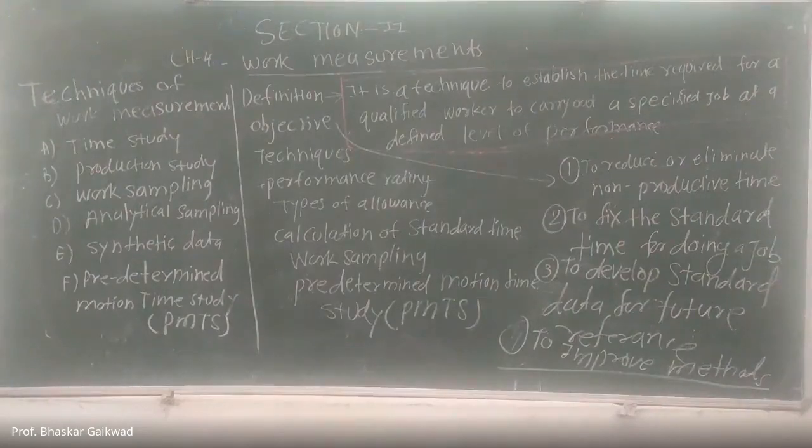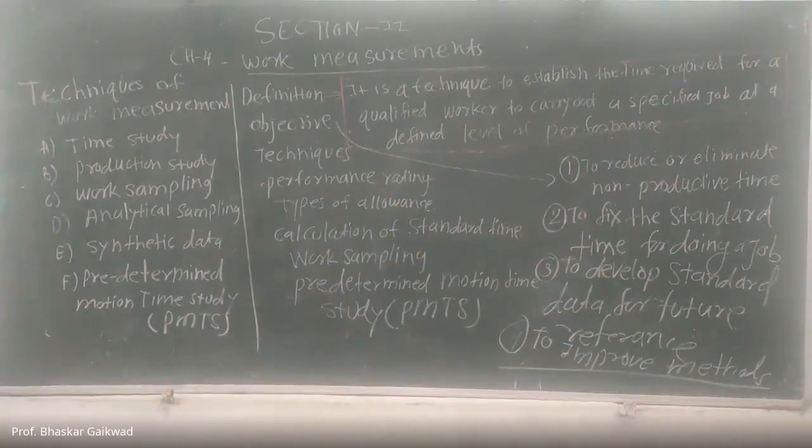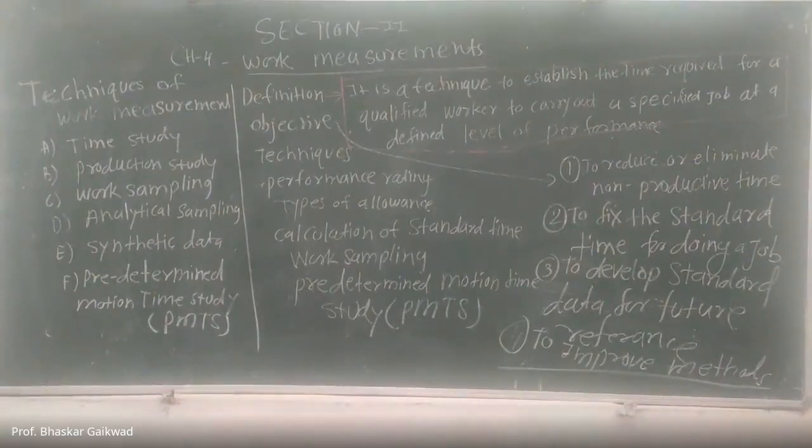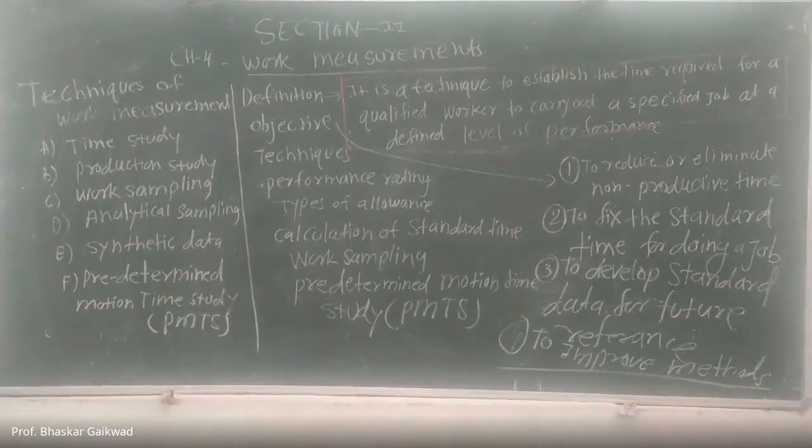And here a gauging system is there, meaning the machine will automatically gauge whether the product is okay as per the program or not. But if you manufacture the same product on a simple lathe machine, there is a problem because manual skill is required to manufacture the jobs. The same skill may not be available in every worker. So depending upon the skill, the job will get manufactured. Sometimes it will get rejected, sometimes it will become undersized, and sometimes more time is required to manufacture.